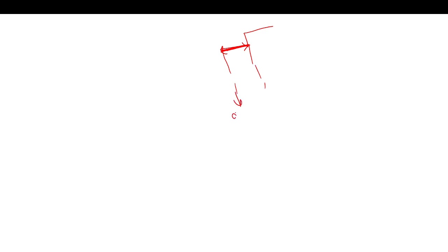Like here, the output is Q equal to say 1, 0. After some delay, it will change to Q equal to 1. The gate delays are very small, usually in picoseconds. So if the clock is only this much, then I won't have the race around condition. Otherwise, I will have the race condition. So this is the problem with the latch.